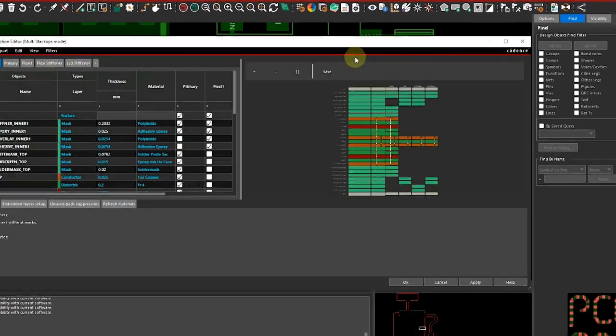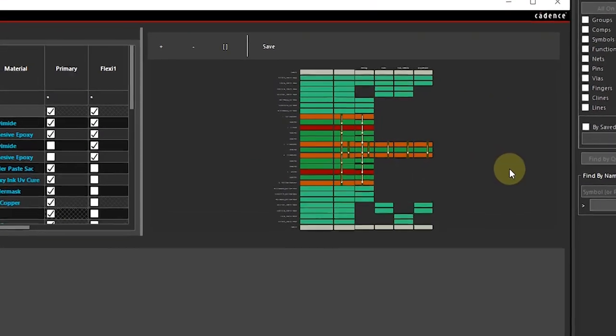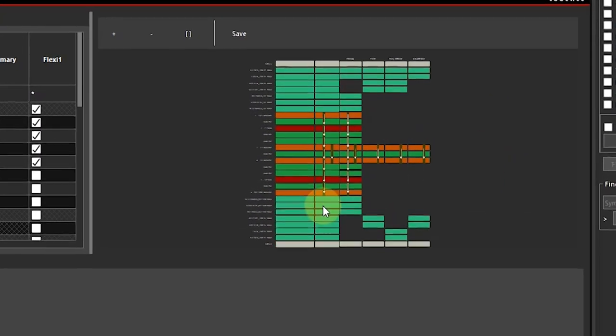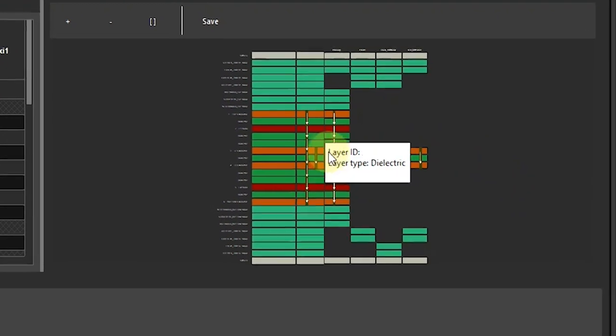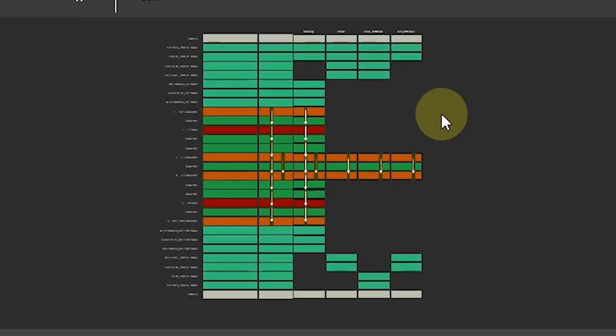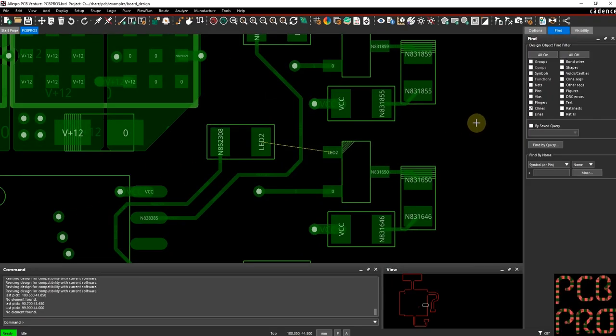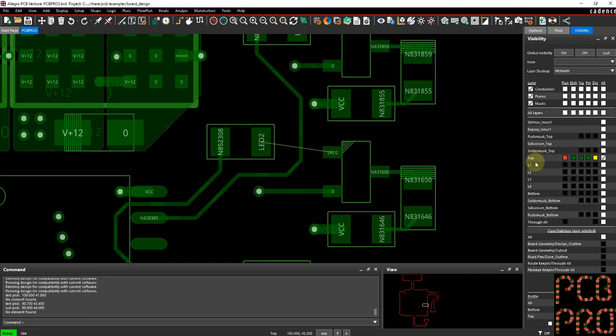Just as a quick overview, you can see in the cross-section editor, I have in my particular stack up already defined a through hole via that I am using, and then also a buried via that's going internally between these two conductor planes. But now what I would like to do is actually set up a blind via, which essentially goes from the top to one of my internal layers. And let's actually keep it simple. We'll do a one layer drop down, so going from top to L1.